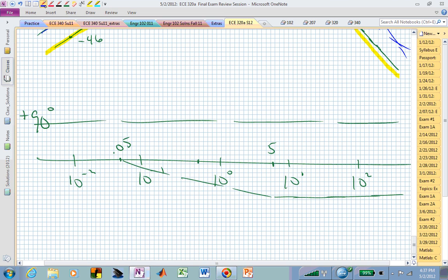And my other factor now was centered on 10. It began a decade before and it turns off a decade after, and it will actually transition over two real pieces, 2 stages of 90. And I'm now going from 0 to minus 180. And what I want to do now is put these pieces together. I'm starting now at low frequencies at minus 90. I start to transition at a slope of minus 45. Whoops, that should have been going all the way over there. But at this point, I need to shut it down at that value.